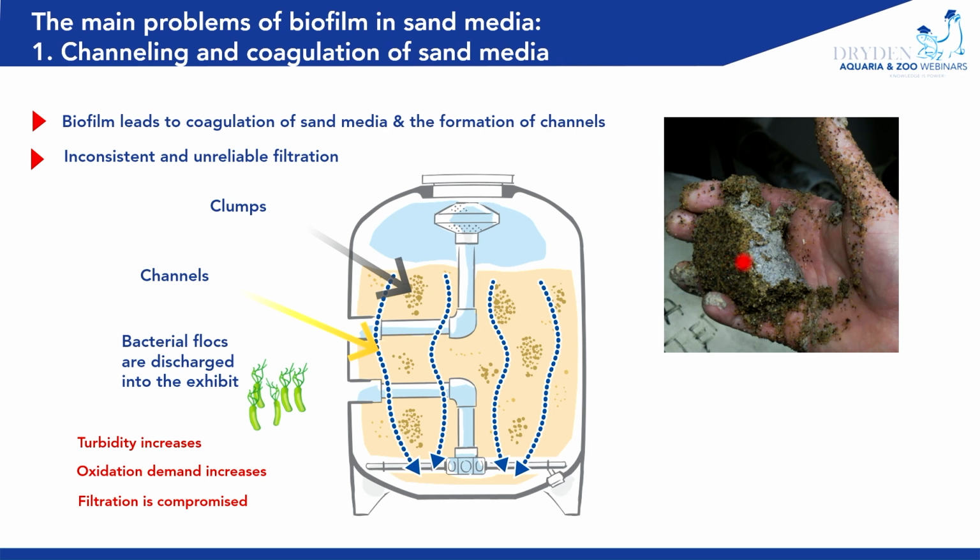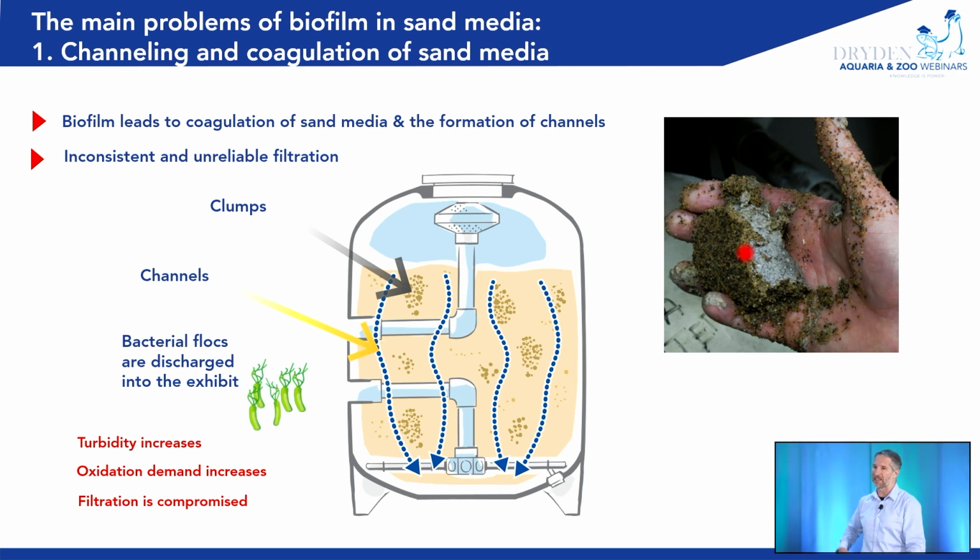This is quite often seen with the increase in pressure losses, a very fast increase in pressure losses, and never being able to bring those pressure losses back down to the original. That means that your sand has started to clump together, and the only time your pressures do sometimes drop is when channeling happens, and that's very inconsistent because it can happen at any time of the day. The channels can open up and then they can collapse again.